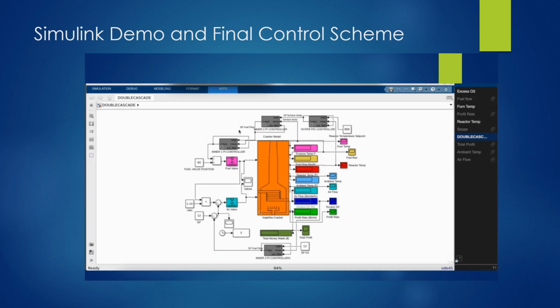In the double cascade controller, three key controllers work together to regulate the naphtha cracking process. The inner one PI controller relates the fuel valve to the fuel flow rate. The inner two PI controller relates the fuel flow rate to the furnace temperature. The outer PID controller relates the furnace temperature to the reactor temperature.